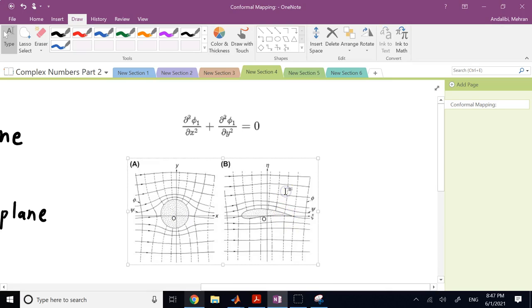So let's say I want to see what the flow around an airfoil is. I'm studying an aerodynamic problem, and these are basically the fluid flow lines. These are the streamlines around the airfoil, and the ones perpendicular to these streamlines, we call them the potential lines. So phi here is the potential field, and you can show that if the flow is not rotational, so there is no spinning in the flow, and this fluid does not have viscosity, or the viscosity is negligible, then the equation for this potential field, these contours, follows this important equation we just mentioned, the Laplace equation.